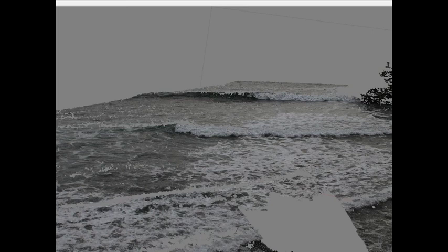Do you have to go afterwards and tell it that you don't like that, or does it come back with a flag that says, I'm not real confident about this, so you can set a tolerance to get rid of stuff? So one of the steps in Photoscan, and if anybody's doing this, I actually have a lot of advice because we've worked on this, the key to getting a good reconstruction is building a sparse point cloud that you trust, right?